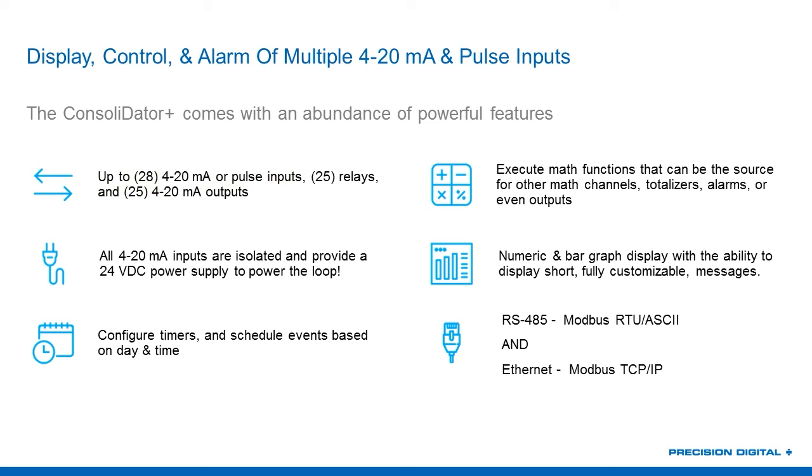Now, I mentioned 28 4 to 20 inputs, which is impressive in and of itself. However, each and every single 4 to 20 input is electrically isolated from one another, and they each contain a 24-volt power supply to power the loop, which is really, really nice. That's 28 power supplies. A lot.